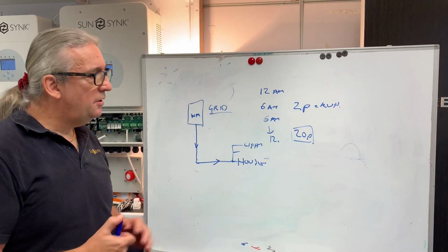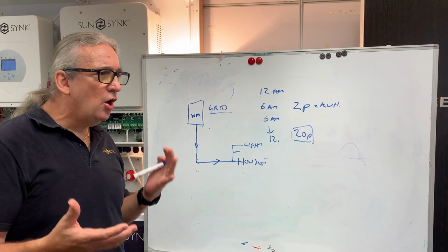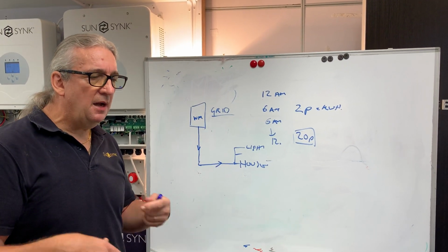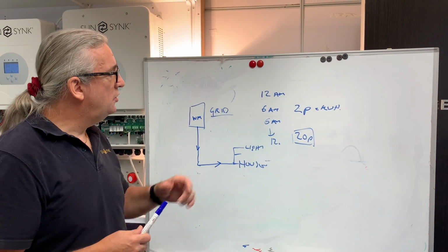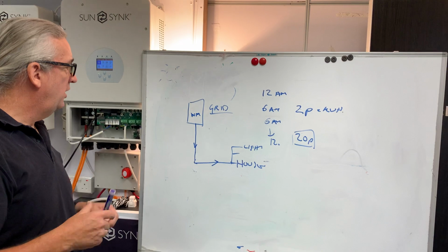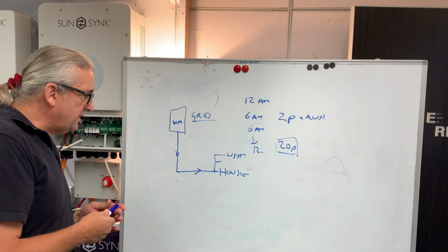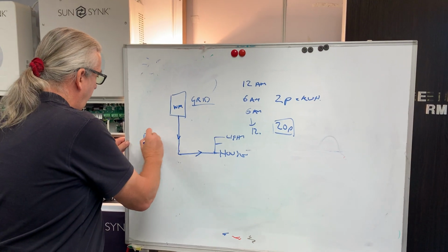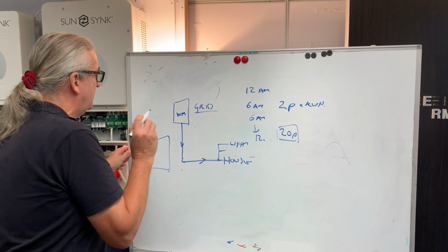So how can we do it? So we store it like the old storage radiators used to have. So they store the heat at night time, and during the daytime they give it out. So you use what they call off-peak electricity, economy 7. So we store the electricity. So what we simply do is we use a timer. So the inverter is here, and then within the inverter it has a timer.